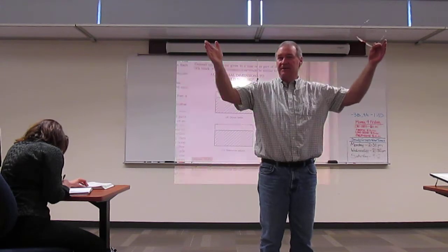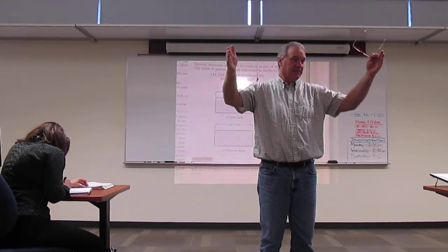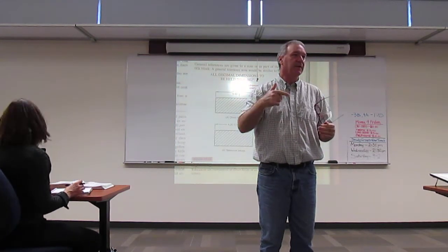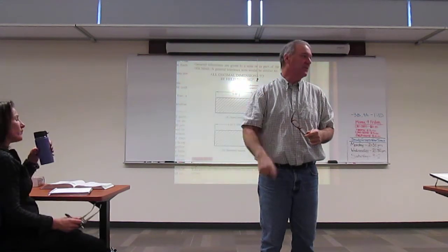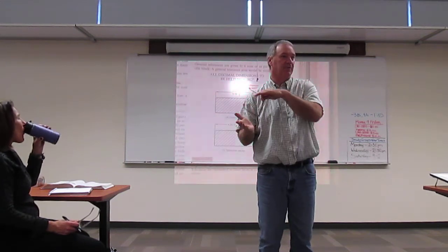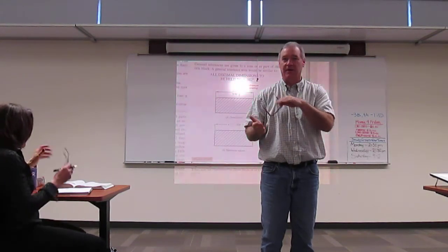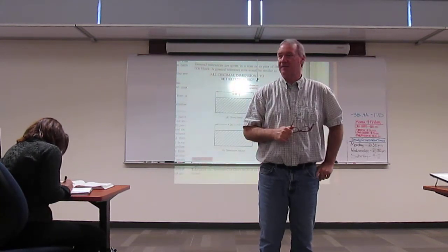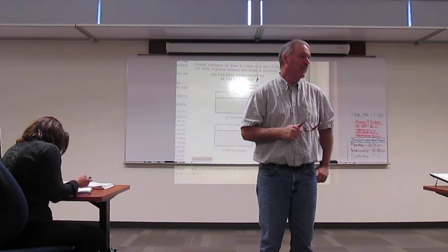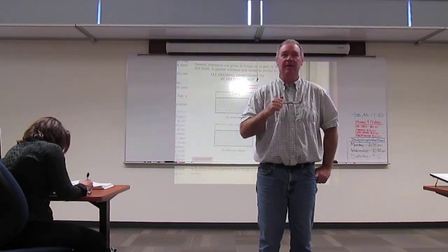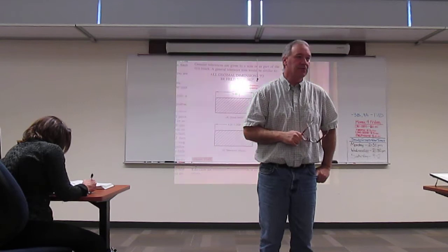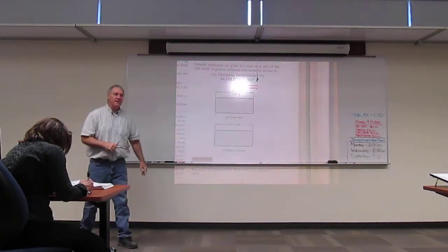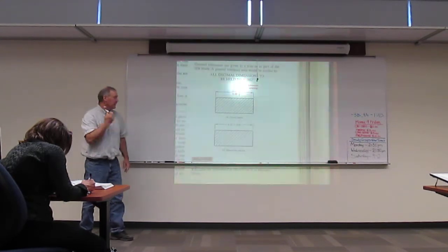Your dimension of width is 6, and you're saying it's 6. Now, if you're doing that in English units, the part will be plus or minus 0.02 inches off of that dimension, and that's a general tolerance. It applies to everything on the drawing. When you start getting mating parts, we move to a direct tolerancing item, and by this we mean applying the tolerance to the dimension in question. Now they give an example right here. These are our 2 ways that we apply a direct tolerance.